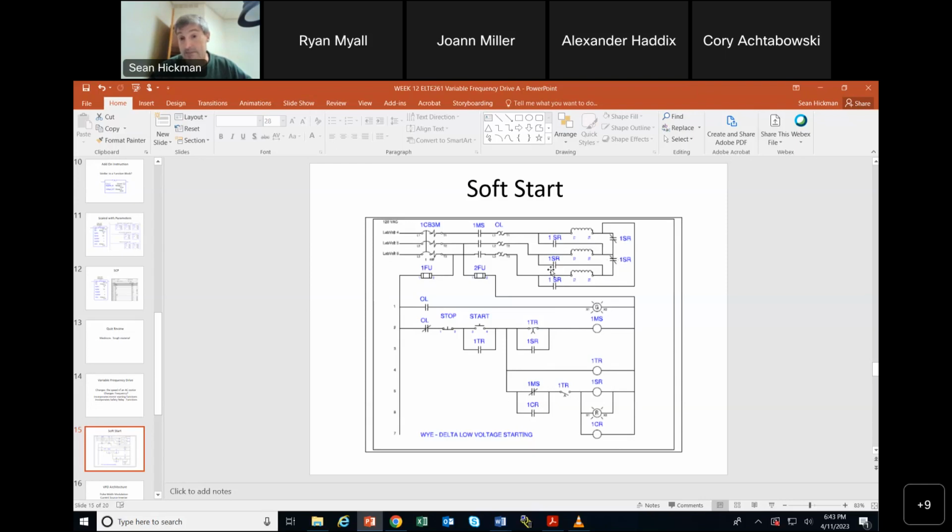So using the same relay for that, we did that as a homework assignment where we put a timer in there. We had two different relays here where these opening ones opened, causing a timer to go on the PLC, which then closed these. So there was no accidental closing of these at the same time. And the same thing here, that's a problem with these relays.